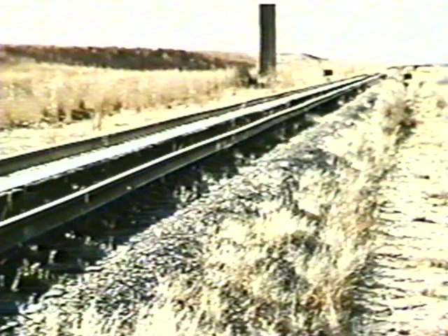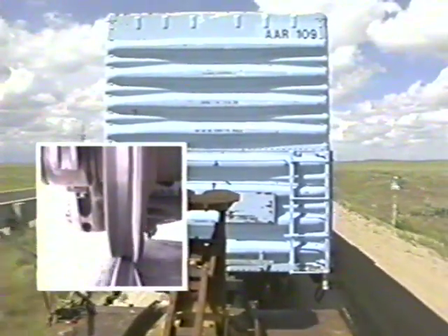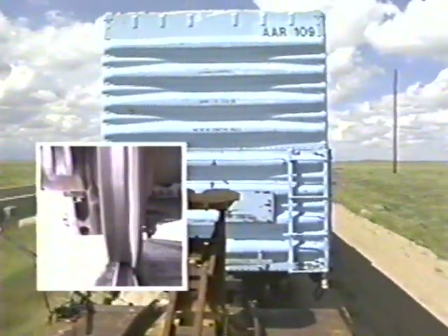rail car. Dynamic roll may result from periodic staggered cross-level changes in the track. These cross-level changes are usually associated with jointed rail track, but may also occur in track with soft ballast or subgrade. If the spacing of the cross-level perturbations and the rail car speed coincide to a critical condition, then complete wheel unloading or wheel lift can occur.